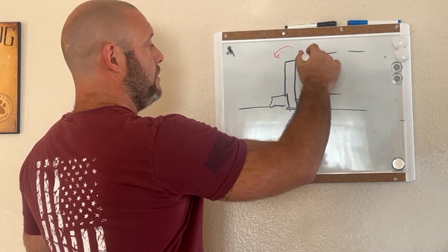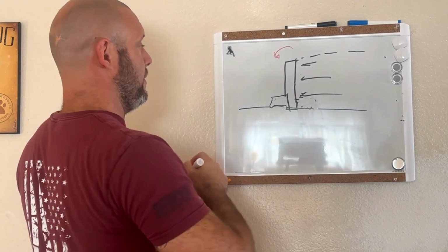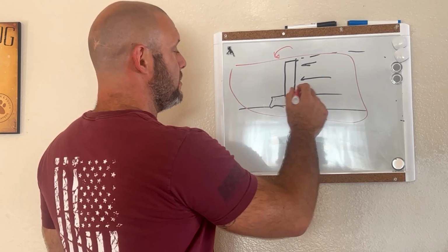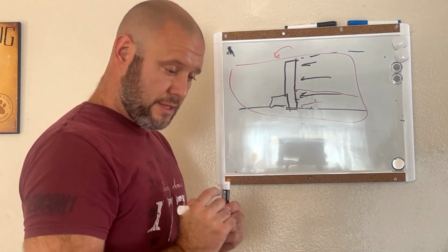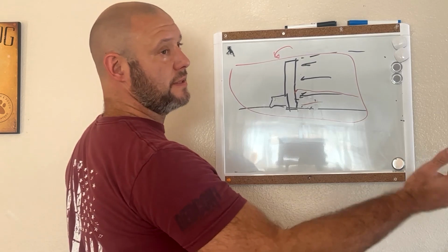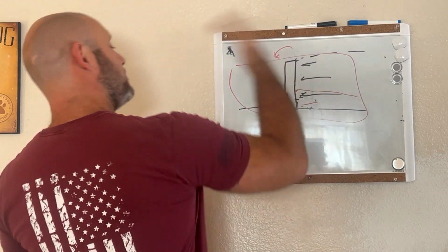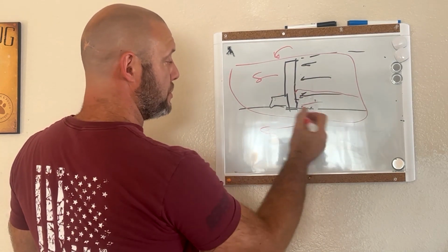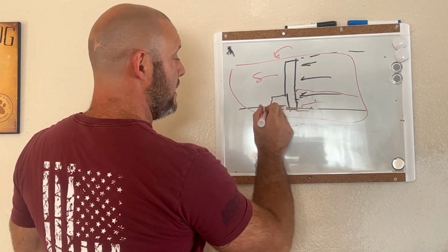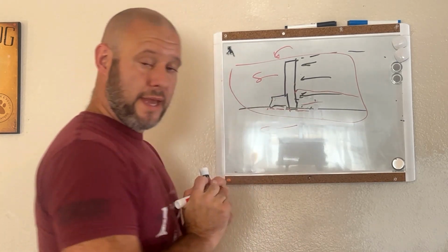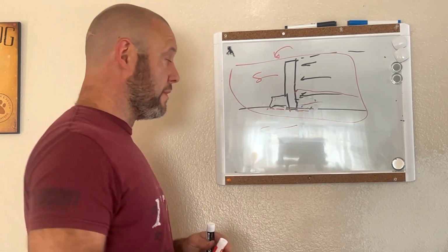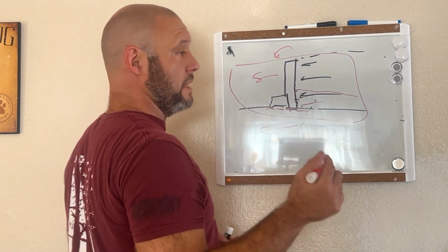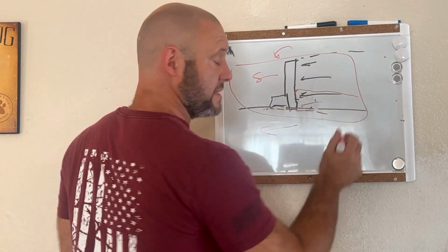But what they do is they end up filling this box back here. They have this whole box, and as they fill it with marbles, when the marbles hit down the bottom here, you realize there's a second mode of failure called sliding. It's when the retaining wall doesn't tip over, but the whole thing just slides. You can imagine these forces are pushing on it, and if the friction gives way here, then this will actually slide on the soil.